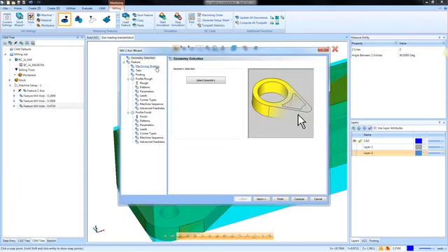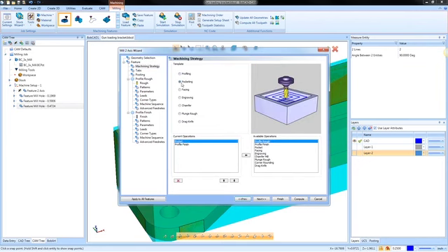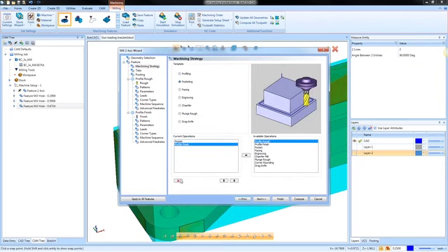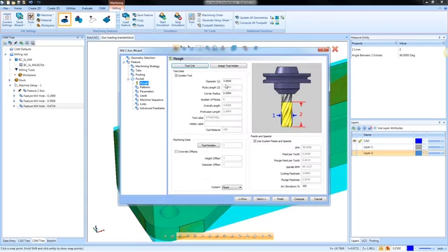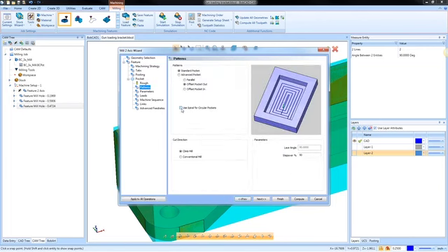From this strategy here, we're going to go to pocketing. I'm going to remove the finish tool, so we have a pocket cycle. I'll go to my tool size. I'm just going to put a 3/8 in here. For my pattern, I'm going to go to use spiral for circular pockets. If you select a circular pocket, you can use a spiral for circular pockets.